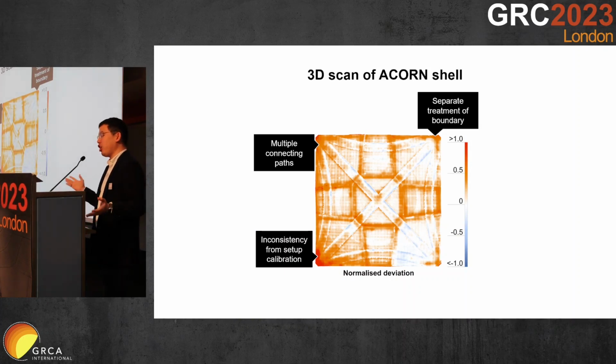Some parts are actually on purpose, so around the borders of each of these segments, we've added extra thickness in order to ensure that the structural performance of the shell is behaving as we want it and not underperforming. And the paths themselves, as they are generated, require path traversals that are not fully accounted for in the calculations, so this results in extra material.